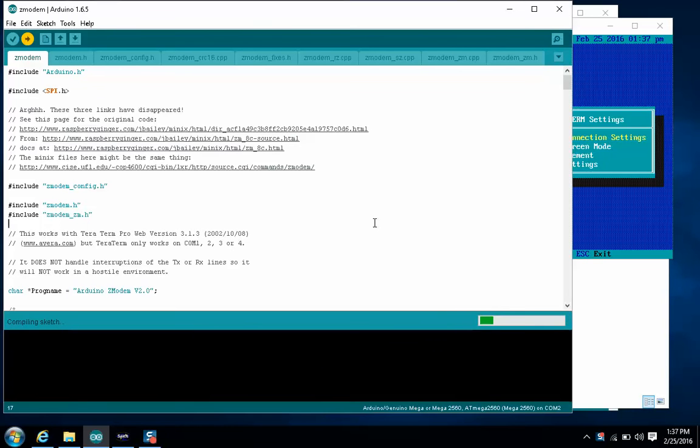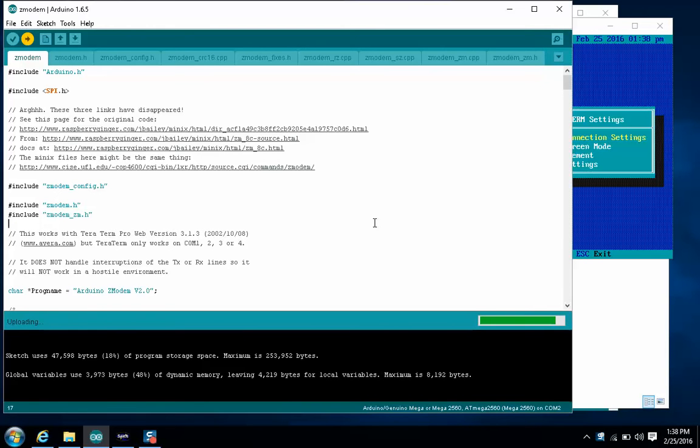So the use case here is if you have an Arduino with a shield that presents an SD card, then you may want to transfer files to and from the SD card without having to remove the SD card from the shield. My Arduino is tucked underneath my car dashboard, for example, quite hard to get at, but I've run a USB cable permanently into my glove box, so that way I can plug my PC in. Unfortunately, the Arduino doesn't present any sort of a drive for the SD card. It's just a serial interface over USB.